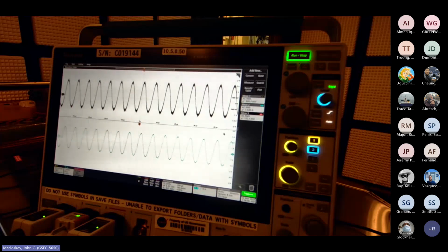And I think for a while, the driver for a specific scope we were using only worked on a straight up RMS value, which forced us into AC coupling the signal we were looking at, which I mentioned on Monday, and we'll get to that when we hook up the unit under test. I really don't like doing that.